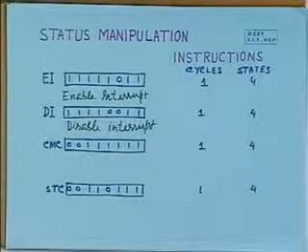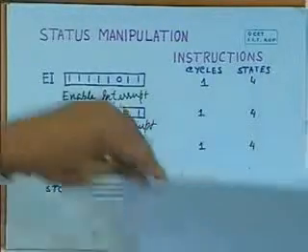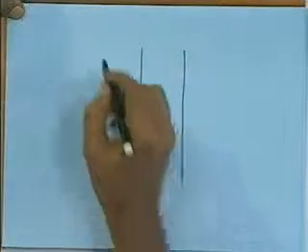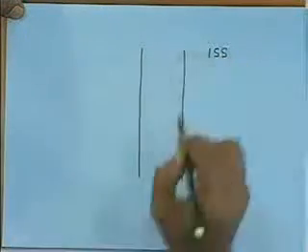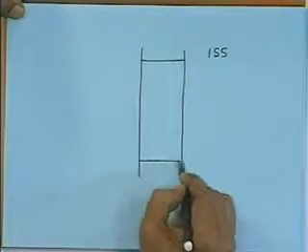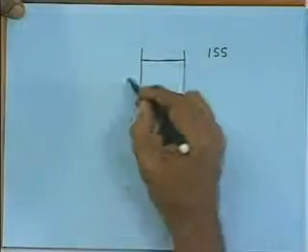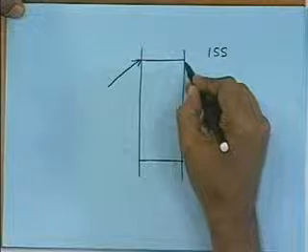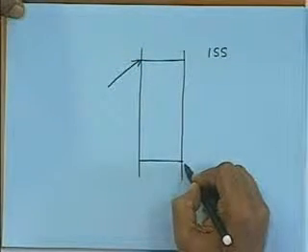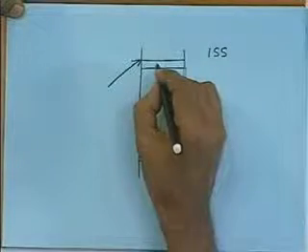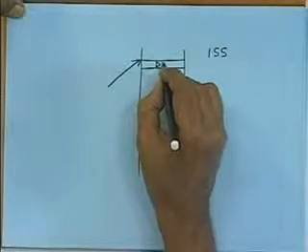That's why, in practice, suppose you have written an interrupt service subroutine. Say this is your interrupt service subroutine, and it starts from here and it ends here. If you want that as you enter this interrupt service subroutine, no interrupt should be accepted, then immediately after jumping to this interrupt service subroutine, you should execute one disable interrupt instruction.